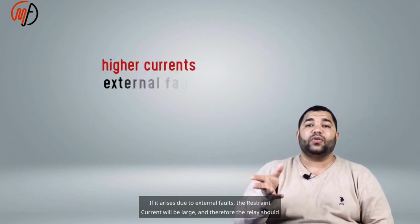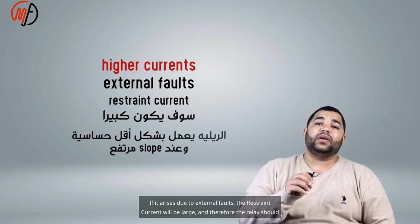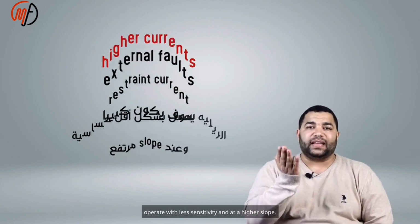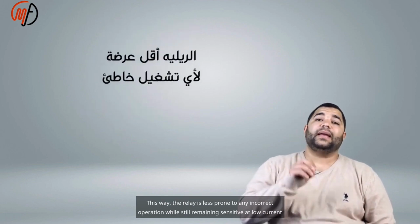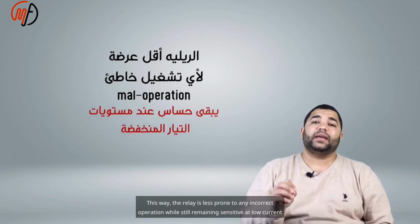If it arises due to external faults, the restraint current will be large, and therefore the relay should operate with less sensitivity and at a higher slope. This way, the relay is less prone to any incorrect operation while still remaining sensitive at low current levels.